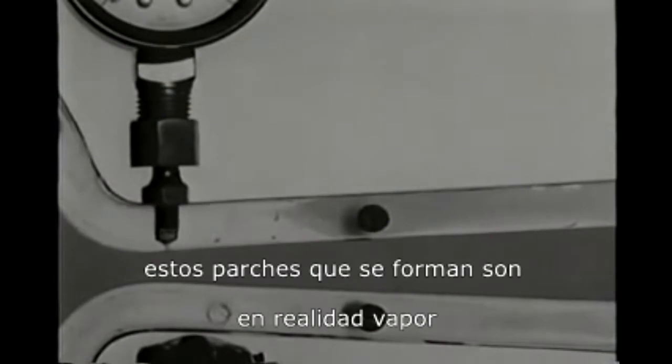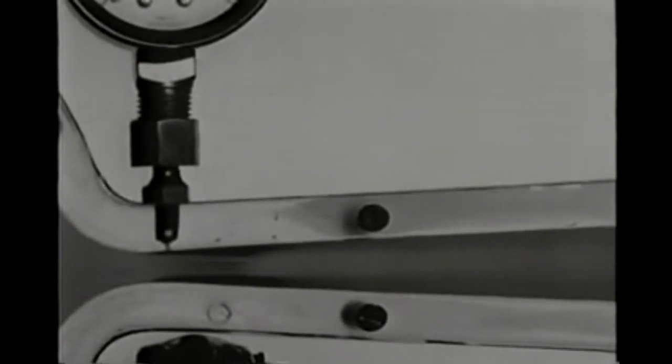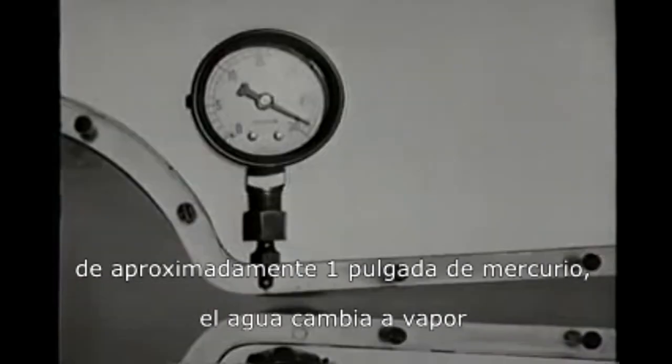These patches that form are actually steam. This is cavitation. When the absolute pressure goes below the vapor pressure of about 1 inch of mercury, boiling occurs.